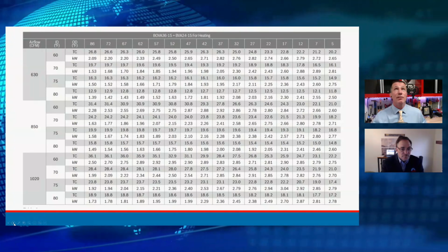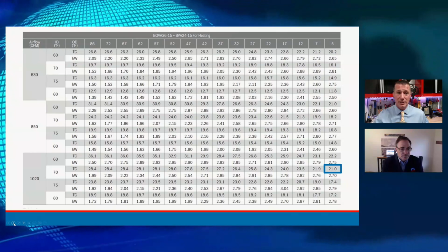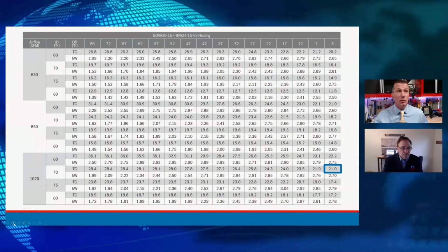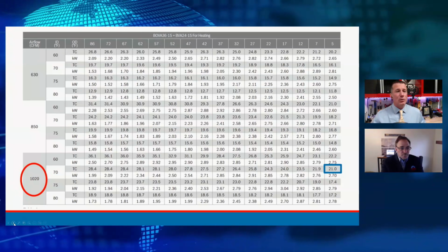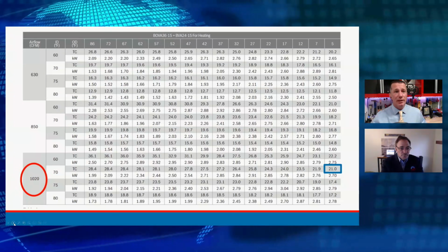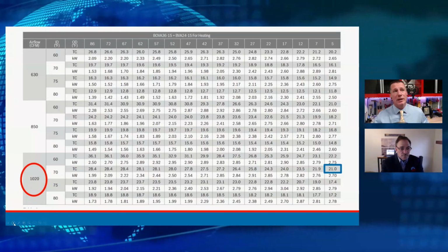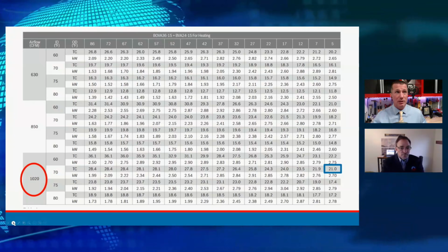If we look at this manufacturer, this manufacturer only takes you down to 5 degrees. This is a traditional outdoor unit. This one actually works with an expansion valve. It can produce 21,000 BTUs, but it takes more airflow. So some of our pieces of equipment can move a lot of heat. We know that if we can move more air, we can move more heat.